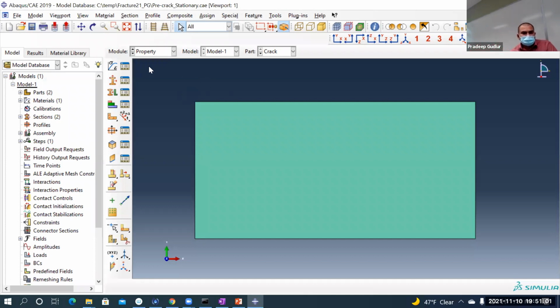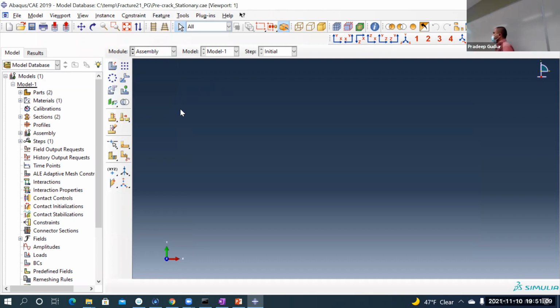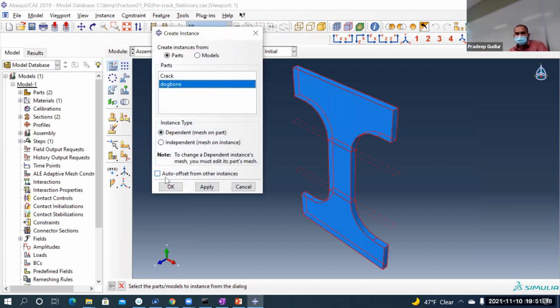All right, so let's go to assembly. I have two parts. Go to assembly and bring in create instance. Let's bring in the dog bone first. Say OK.